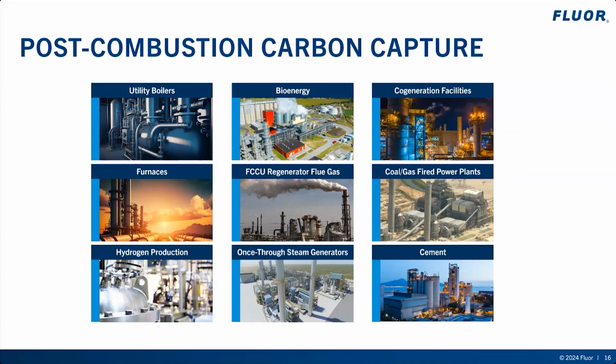Similarly, amine-based technology solutions are effective for flue gases high in other contaminants such as particulates or sulfur oxide species when the right pretreatment steps are applied to the flue gas upstream of the CO2 removal step. While the technology is broadly applicable, carbon capture plant design does not lend itself well to a one-design-fits-all solution.